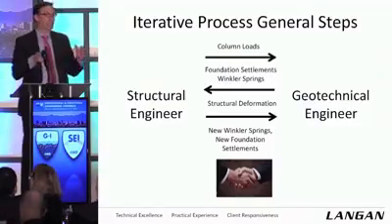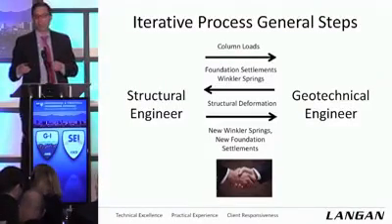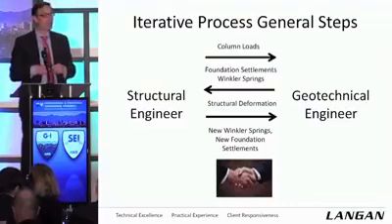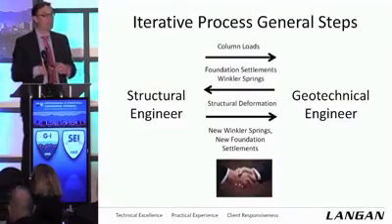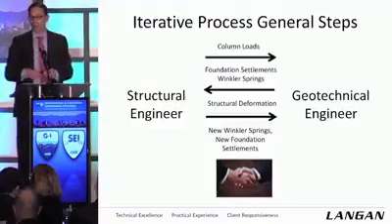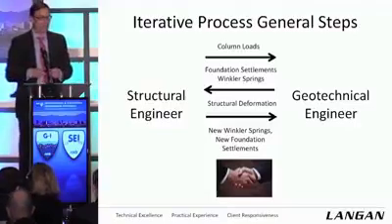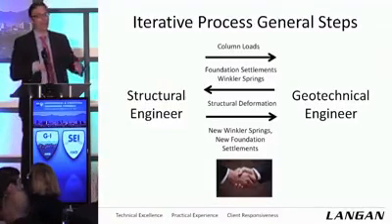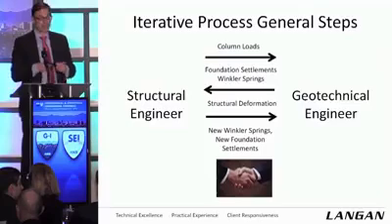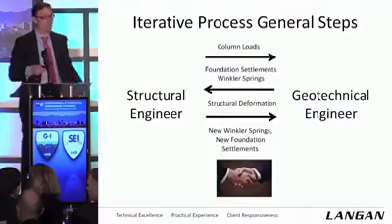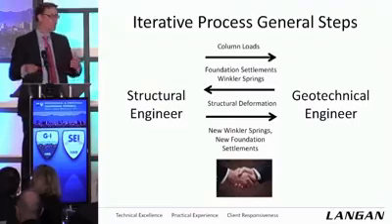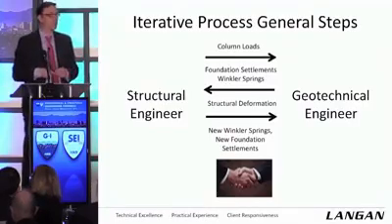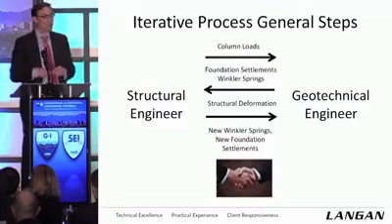And determine settlements, determine pile loads, and also bearing pressures under the raft. Calculate springs both for the piles and for the subgrade modulus. Give those back to Bob and his team. They'll run it through, I think they were using ETABS at this point, and in some cases the wall loads will change. So we take those new wall loads and put them back into our model and get a new settlement profile, et cetera. So we go back and forth like that.